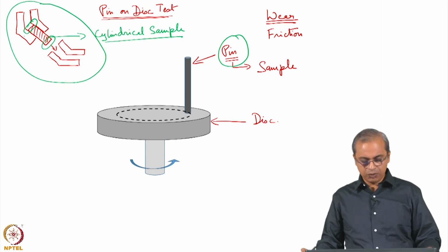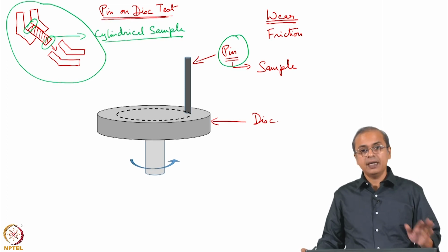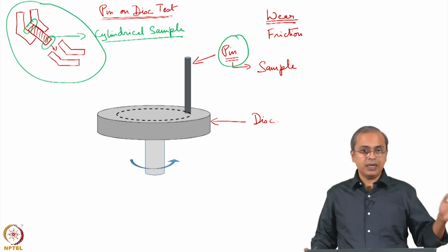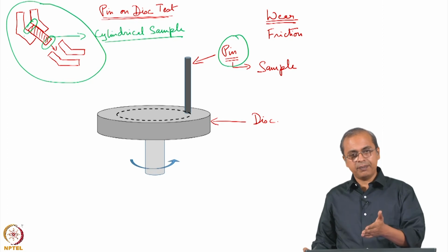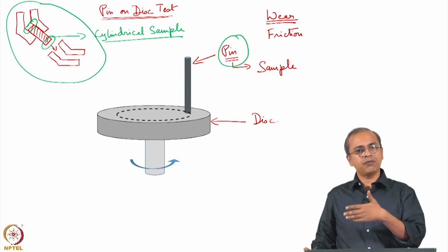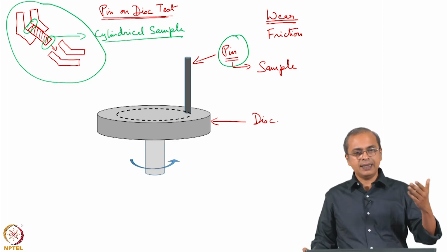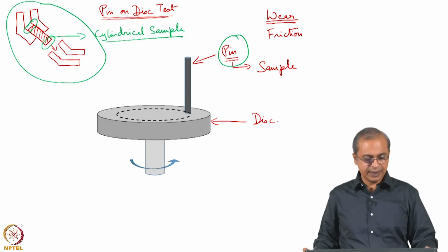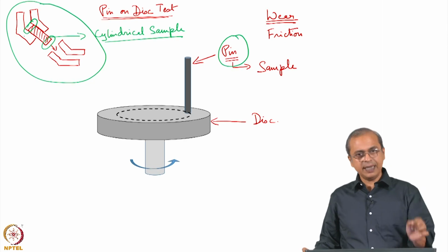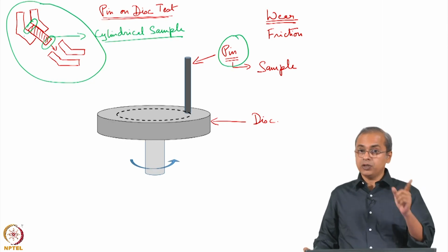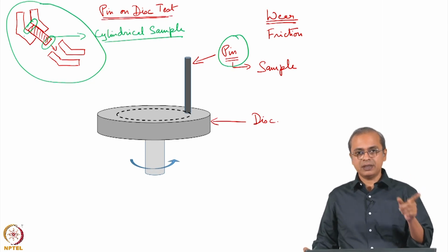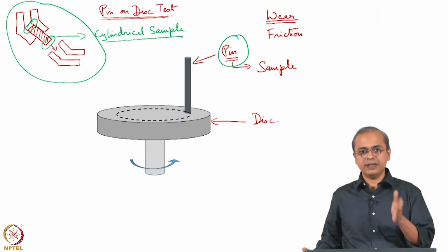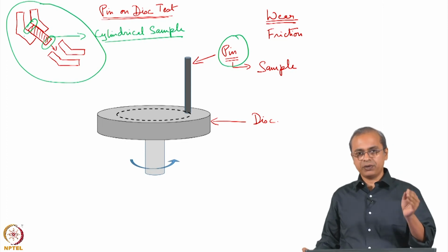But generally you are going to get a pin, and you can get it in nanocrystalline, microcrystalline or macrocrystalline form from some commercial entity, and then subject it to severe plastic deformation such as equal channel angular extrusion, and the same pin you can now get in nanocrystalline form. So, you can get the same sample in microcrystalline or macrocrystalline and nanocrystalline form, and that is what we are always interested in if we want to study the effect of the nanoscale.